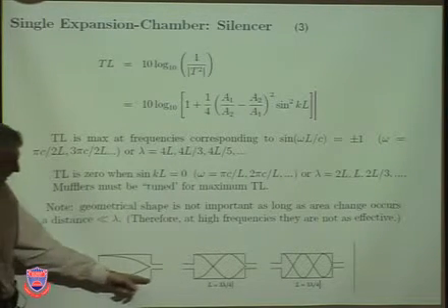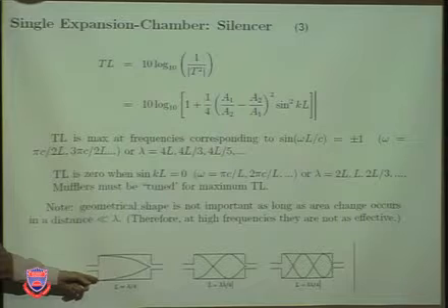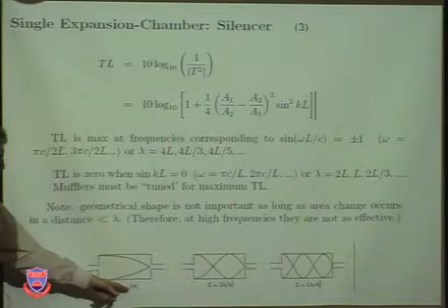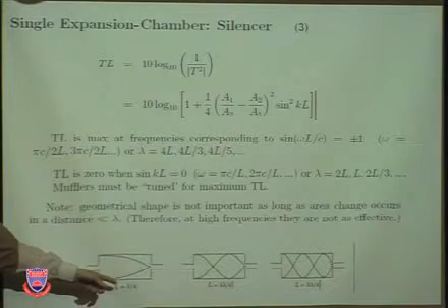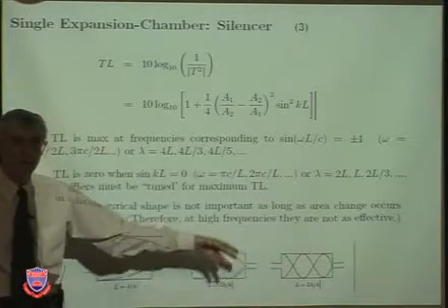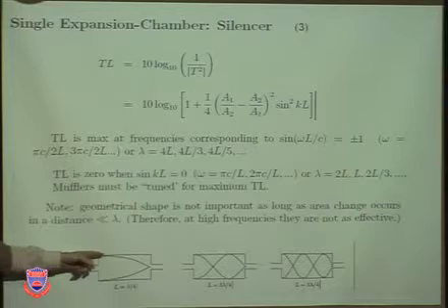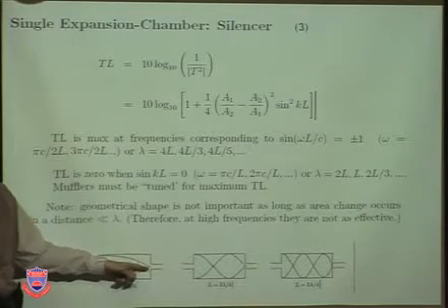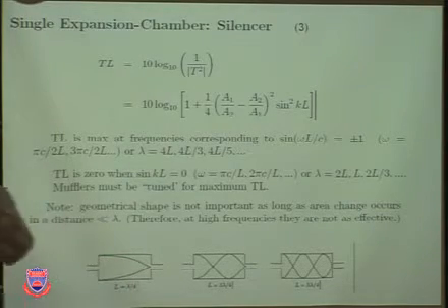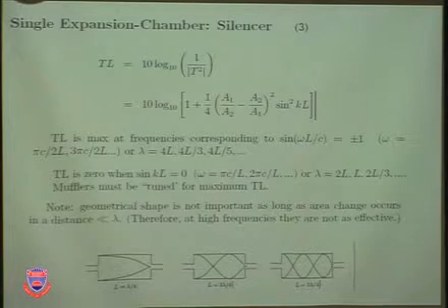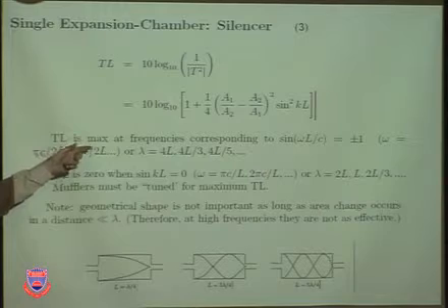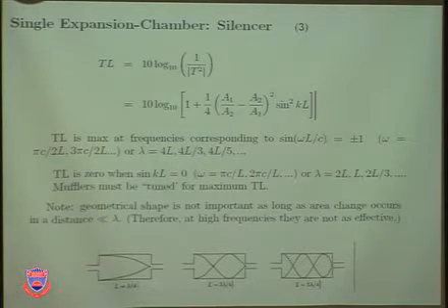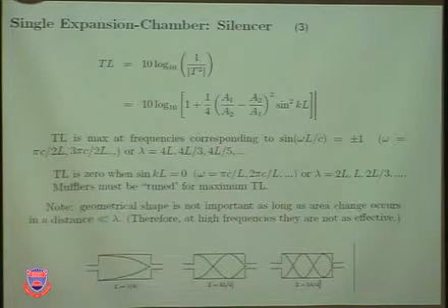Okay, we select the length such that at that frequency, it corresponds to 1/4 the wavelength, or 3/4 or 5/4, so that the pressure at the other end is at a nodal point, 0. That's what this means. Okay, when that's the case, then sound pressure just does not propagate effectively in the other direction.